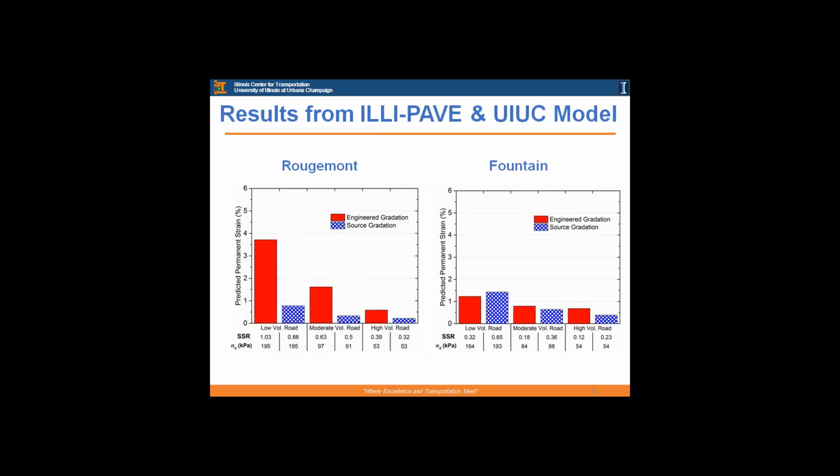All the permanent deformation models, if you look at the past for subgrade rutting and granular material rutting, they're not meant for granular material rutting actually. But anyway, strain-based, like you said, Hassan, I think that's a very good point. If you look at how they come up with different coefficients and model parameters, those values were all over the place. It's very hard to get a fix on strain level. Strain levels will change according to different pavement configurations, how thick they are, and how they're loaded. And they're not robust as opposed to controlling stress.